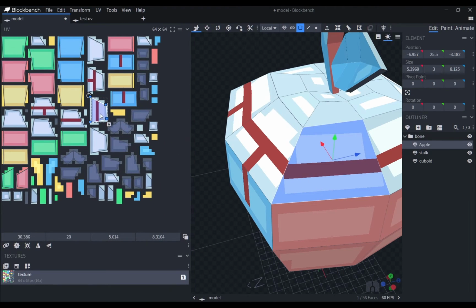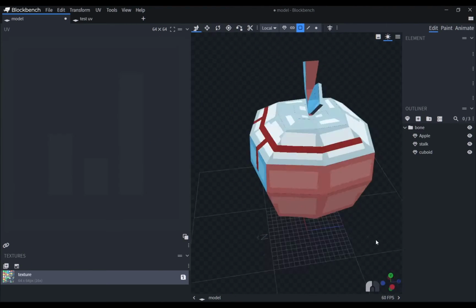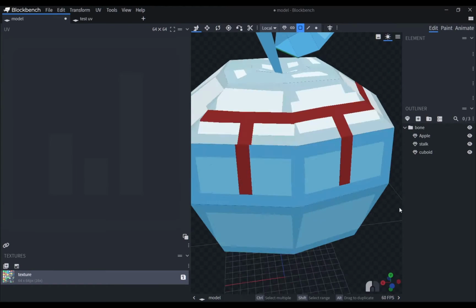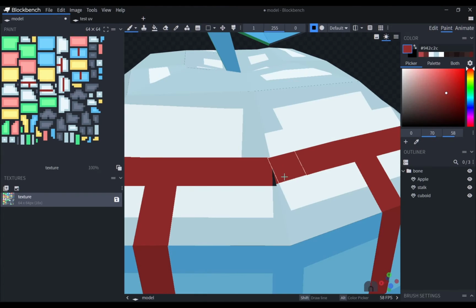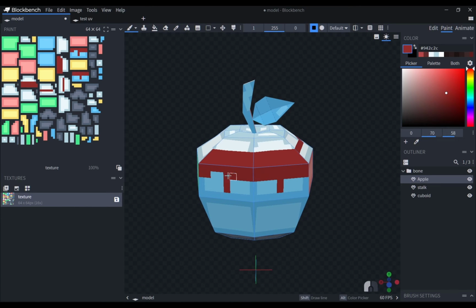Then, click the corresponding plane in the UV window. To make adjustments, use the arrow keys along with the Shift and Control keys to control the increments. Then repeat the process for all the faces that need an adjustment. Now, all the texturing problems are solved. We can now freely texture the model without any hassles.